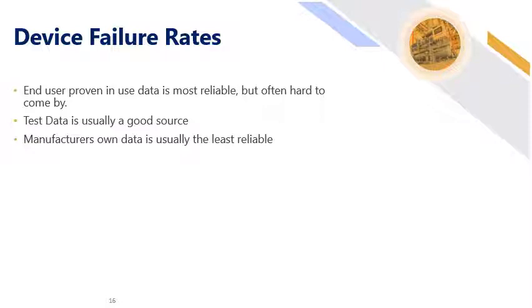If you can't find that sort of data, then there are other sources of information that can be found, such as exida or a reader that gives you generic information from other plants, and that can be a good source to base it on. And exida do test data as well, so you can actually get a certificate that says that this specific instrument is rated to a particular failure.